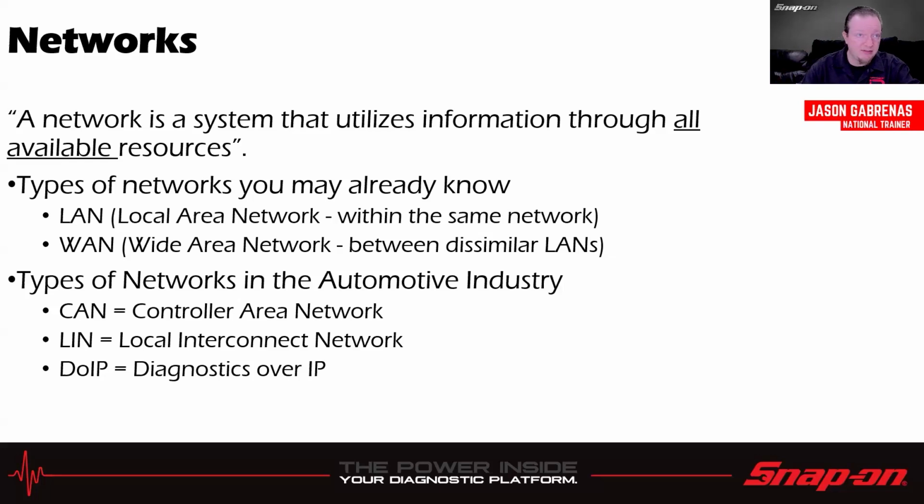So in the vehicle sense, let's say RPM is sent out by the ECM and the TCM needs it, and maybe the anti-lock brakes need it for some reason. Vehicle speed comes out of the transmission perhaps, and then traction control would need that, or whatever the combination is. But they feed information to all the other modules that might need it on the network.